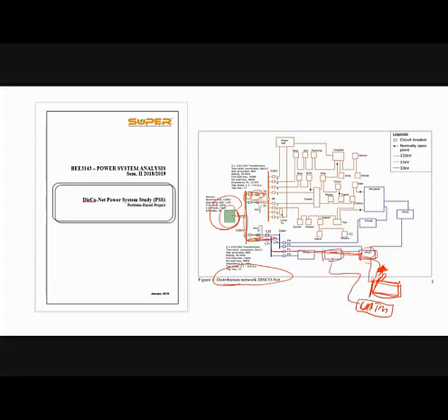If this UITM wants to take power supply from the same substation, we have to study whether this substation can supply this much power to the UITM. That's why we have to do the power flow analysis. We have to know what is the maximum current that will flow in this line, and whether the transformer over here can withstand the maximum power to this new load. If it cannot withstand, what size of transformer is suitable to supply the new load.